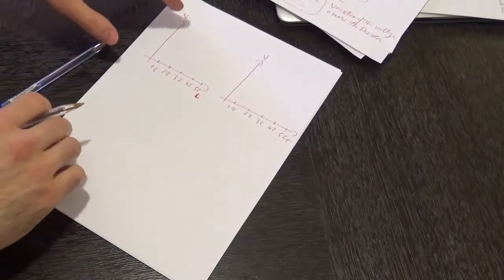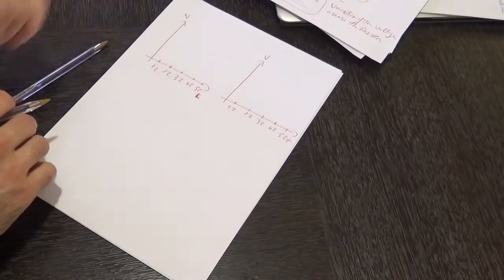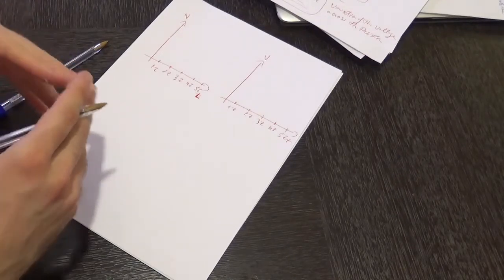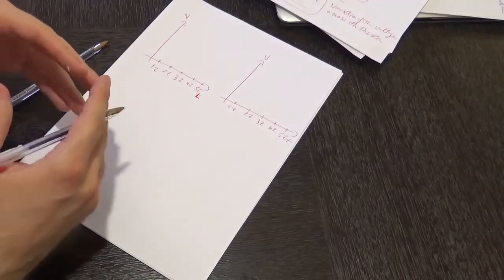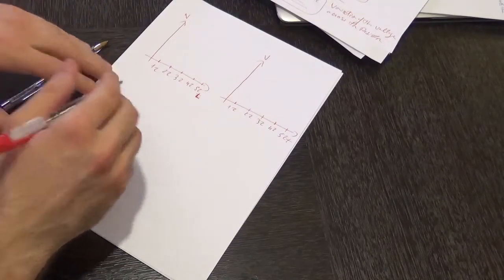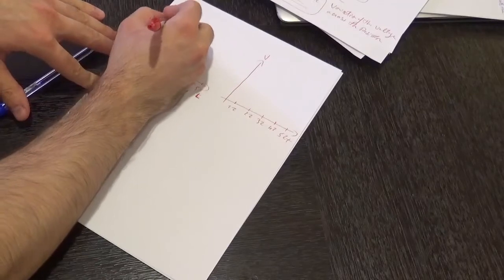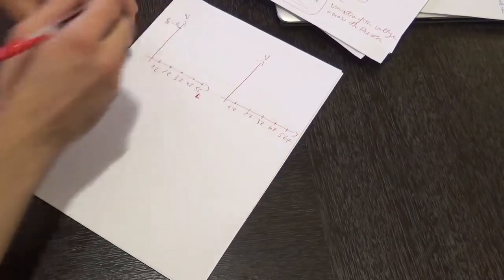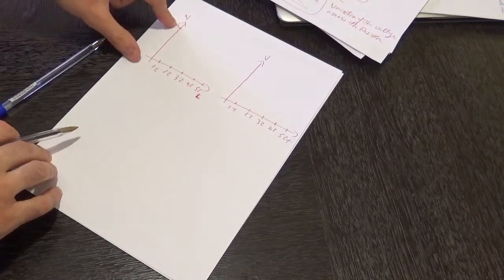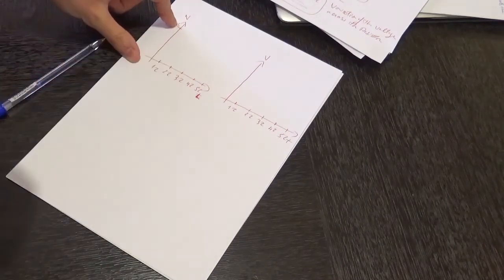So starting with the voltage, let's say across the resistor. The voltage across the resistor starts at the maximum value the moment we close the switch. So for the resistor, we are basically starting at VR equal to V0. Initially the voltage across the resistor was equal to the voltage of the battery. So we are starting from the possible maximum value.